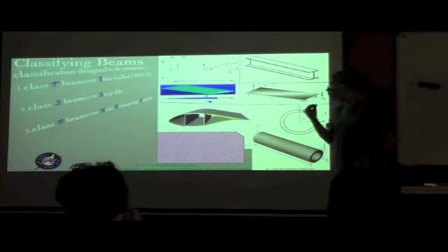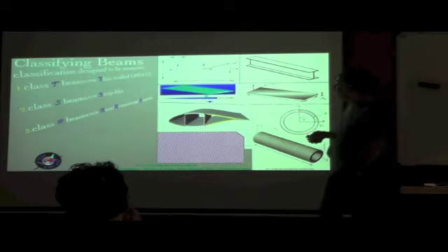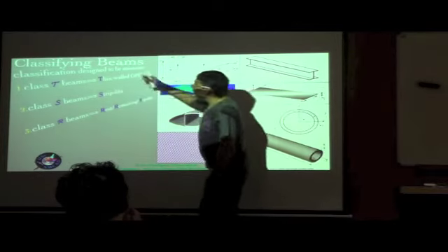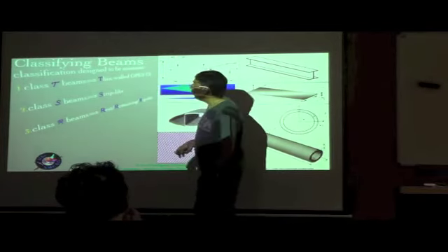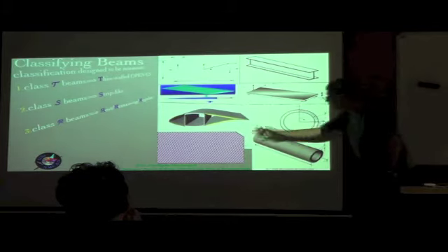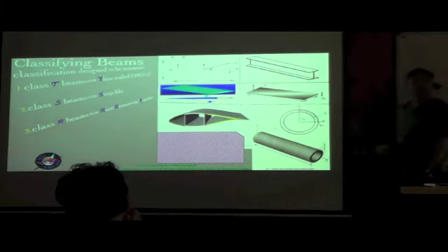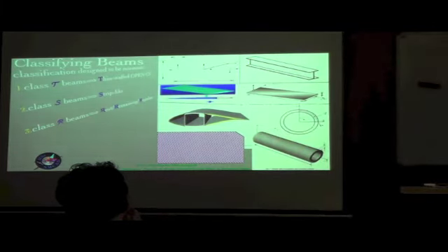The nonlinear effect would be very minimal. But basically, these are the three major classifications that you have: thin-walled open cross-sections, strip-like, and the rest of the cross-sections, which primarily include solid cross-sections and thick closed cross-sections.